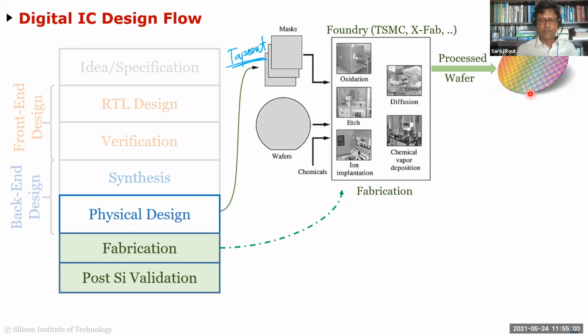So let's say you have 1 million parts. Out of the 1 million, if your yield is 99%, then 10,000 parts will be bad. So you want to throw those bad parts out. What they'll do is take this wafer and do wafer level probing, where they probe with really micro probes and find out if your chip is working. If it is not, they'll mark that particular portion of the wafer with a dye, like an ink dye. Okay, so that's why it's called dyes. And then when they cut and dice it and you start packaging, whenever you see that ink dye, you'll just throw it off. You'll say, okay, this is a bad part.